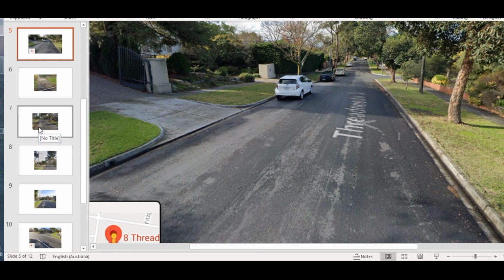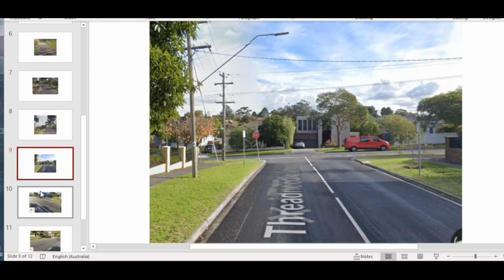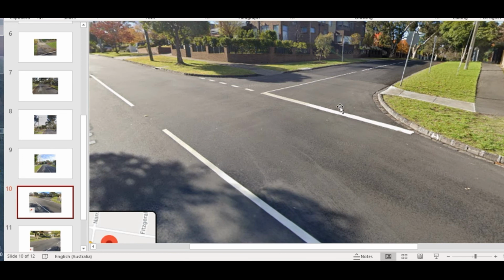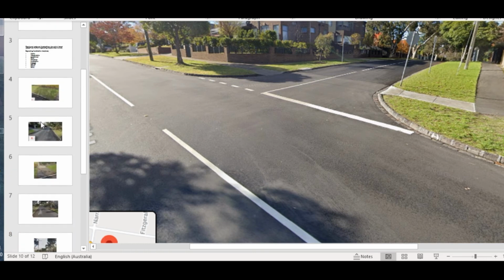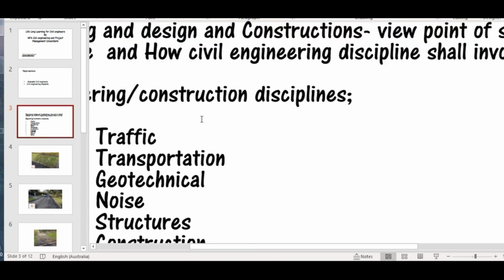So these are all the factors we shall take into account when we design the drainage system, so that we don't see overflow when a particular event occurs. Again, we decide how much occurrence, which average recurrence interval, and which event we are using to be able to design inlets. So this shall be involved as a part of engineering as well.